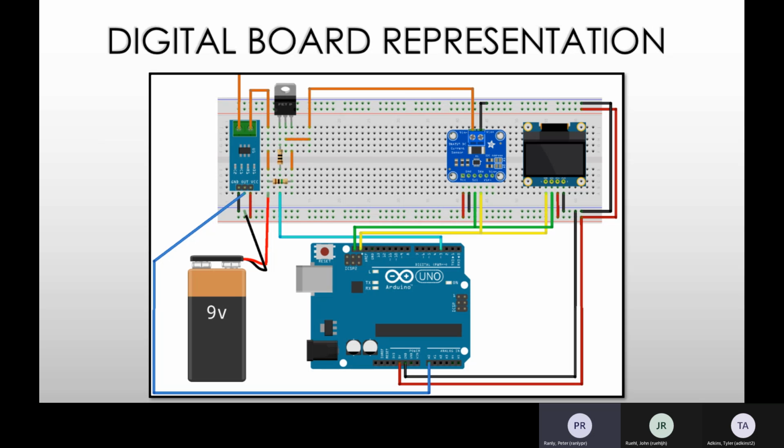The module in the center measures the voltage with a small shunt resistor and reports the voltage back to the microcontroller with I2C code. The right module is an OLED display that will be used with our prototype to display the voltage and current live, and it also uses I2C code. Lastly, a 5-volt DC signal from the Arduino is sent to the gate of the MOSFET to switch the MOSFET on, and this will be used when multiple strings are connected.